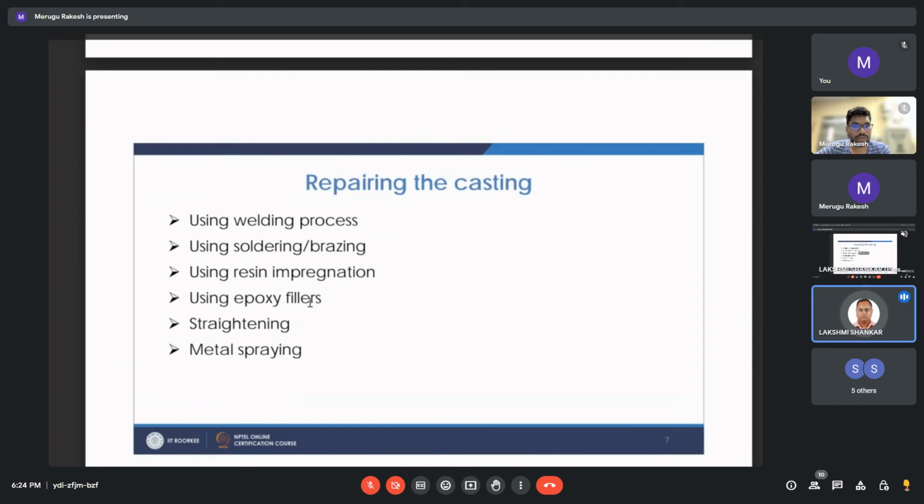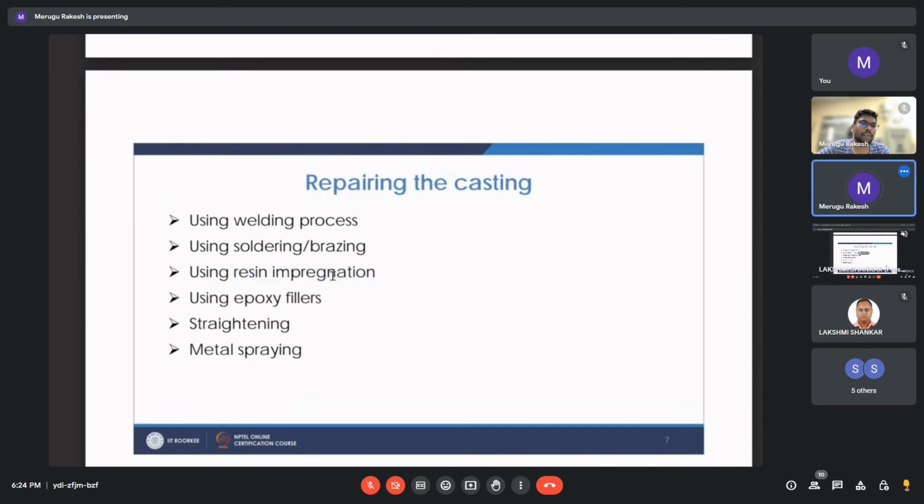Sir, what is resin impregnation? If we have small blowholes, small pinholes, or any kind of defects, we put the casting in resin and apply some pressure, so that the resin goes into those blowholes and fills the gap. That is what resin impregnation means.